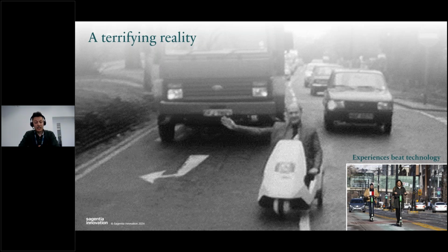It had fundamental issues with technology. The battery drivetrain of that period were not particularly sophisticated, so anything more than, say, a 4% incline, the battery wouldn't have enough power to get you up the hill. It would cut out and you'd have to resort to your backup pedals. So you can imagine, as a sustainable consumer trying to get to work on your commute, battery cuts out, up a slight hill, and it's 99 kilograms, this device, so you'd get to work very, very sweaty. So just not a nice user experience. Interesting technology, but fundamentally the experience let it down.